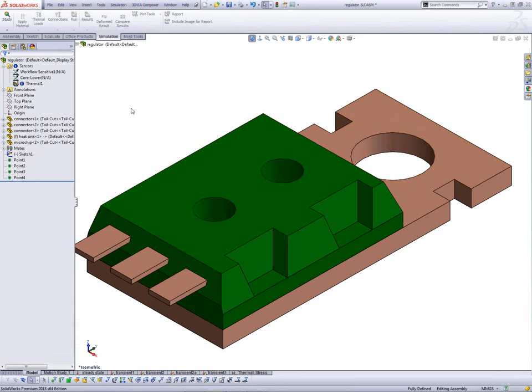Here's a view of that model, showing just the SolidWorks tree now so we can understand how these sensors are set up. If I show my sketches, you'll notice I've got a sketch in here that's buried within the solid for the integrated circuit chip. I've got some sensor data set up for the lower half of this grid, and I want to demonstrate how we can set up more sensor points to monitor the upper half.